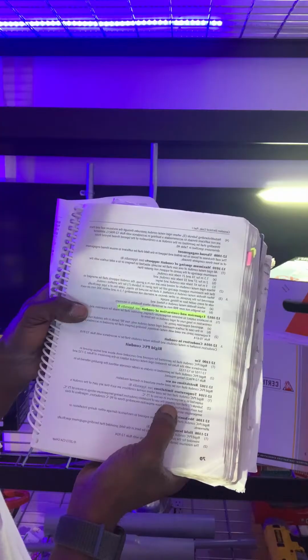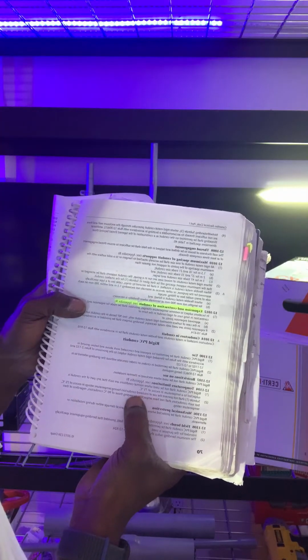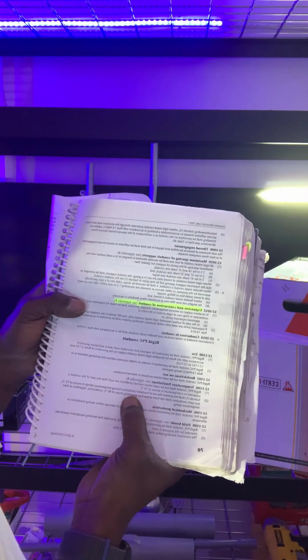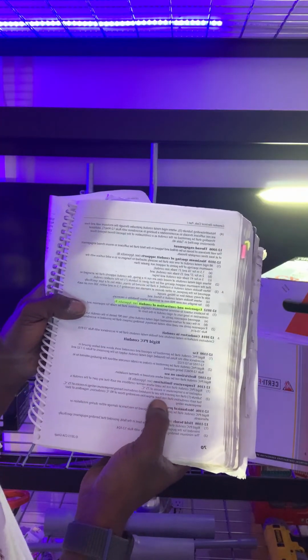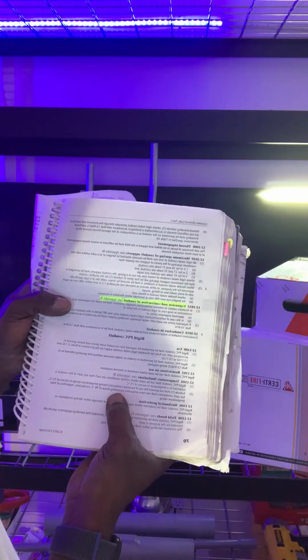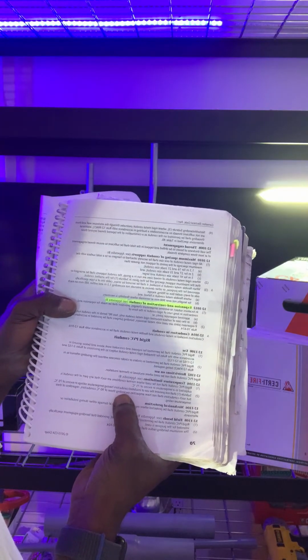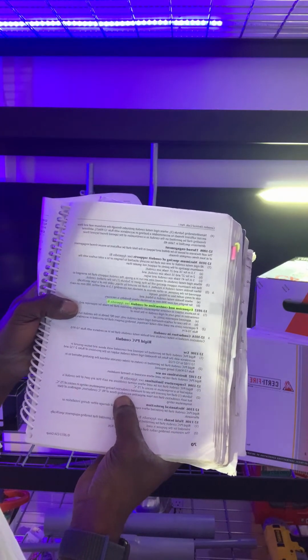Subrule 1 shall not prevent the use of insulated conductors having temperatures rated in excess of 75 degrees Celsius, but such conductors shall not have ampacity exceeding those of 90 degrees Celsius conductors, regardless of their temperature rating.